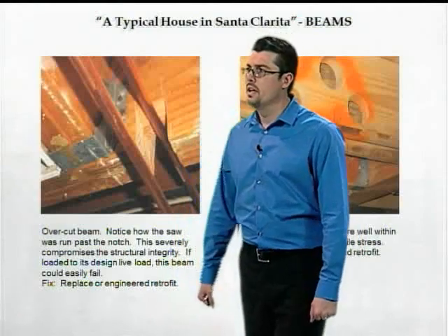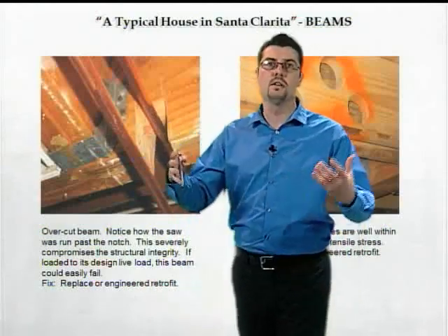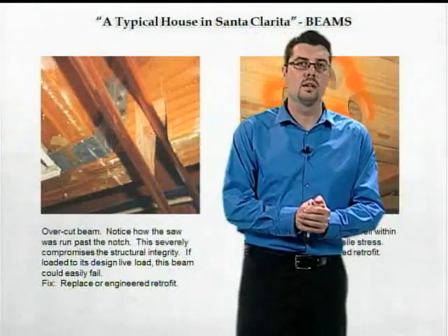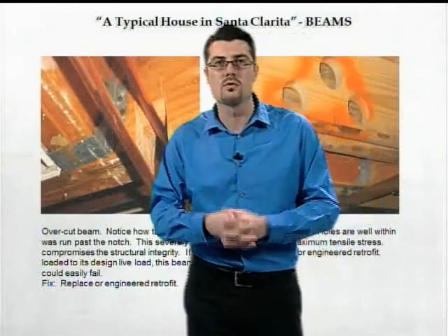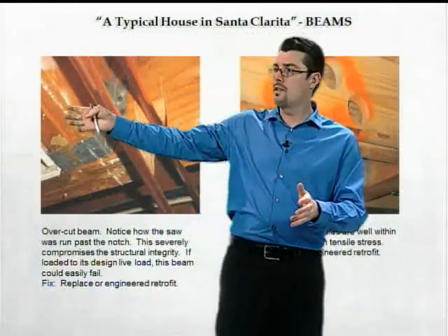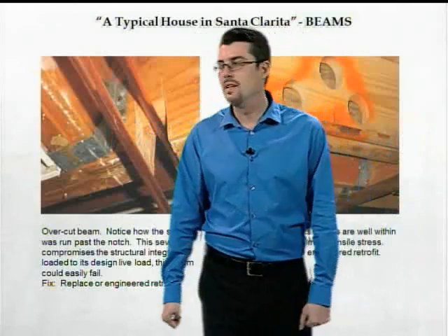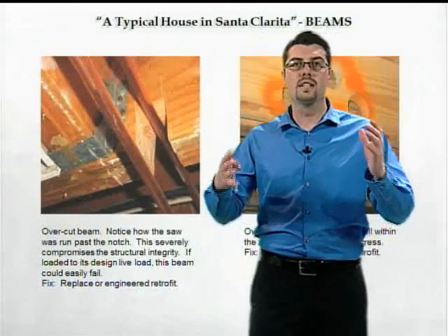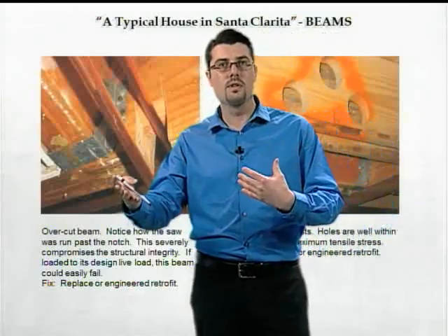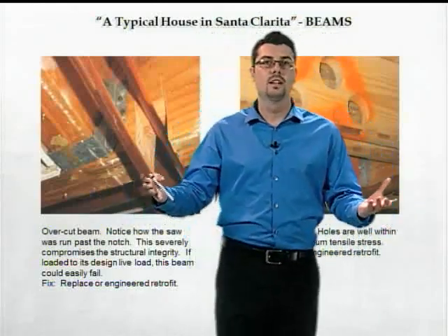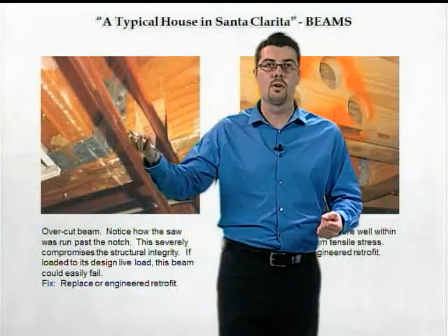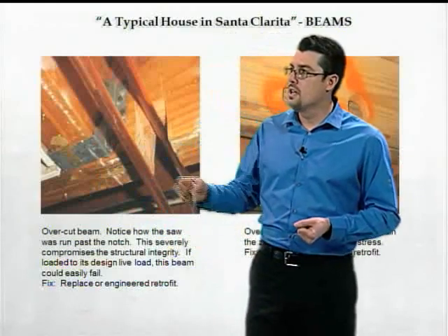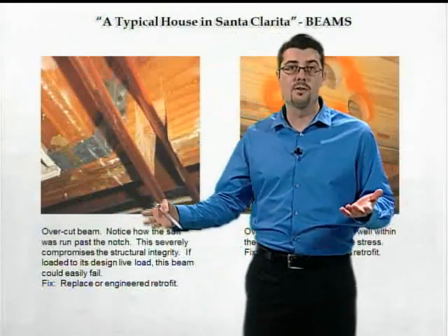Now you might wonder, when you sometimes go out and you see big errors like this, holes cut in beams and severely compromising the structural integrity, you might ask, well, how come that thing's still standing? Why doesn't it fall down? And one thing to keep in mind is we design structures for dead and live loads. And the live loads that we design for are loads that aren't always there. They might only be there for a short period of time during the life of the structure. So in a situation like this, they're just lucky that the live load isn't there.